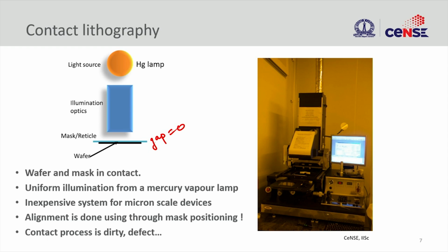The only problem in this contact process, though it is very simple and you don't need to worry about the gap and so on, this is a contact process. So what this will do is it will make your mask dirty, or it will pass on the dirt in the mask onto the wafer. This will eventually result in defects in the devices that you are making.